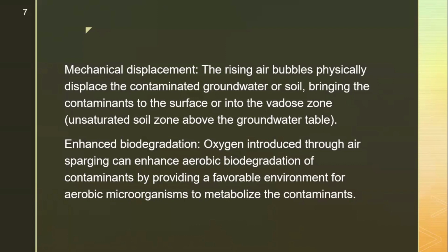In situ air stripping can enhance biodegradation of contaminants in groundwater and soil by enriching the subsurface environment with oxygen. By injecting air or oxygen into the contaminated zone, this technique increases the availability of oxygen, crucial for aerobic biodegradation processes.